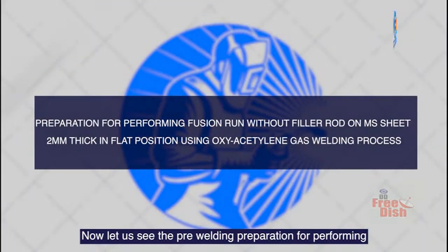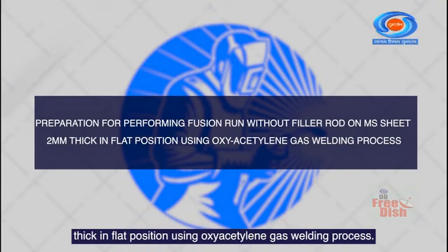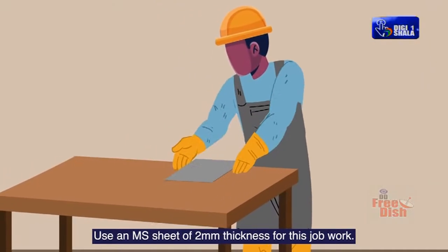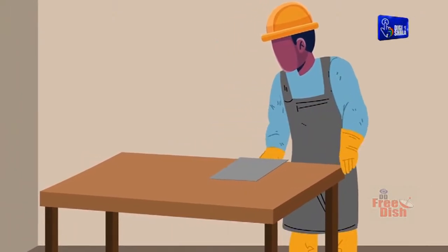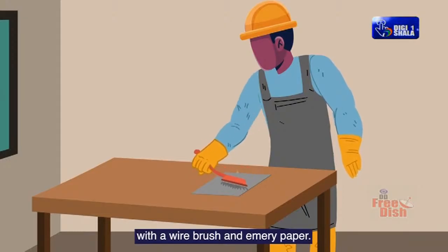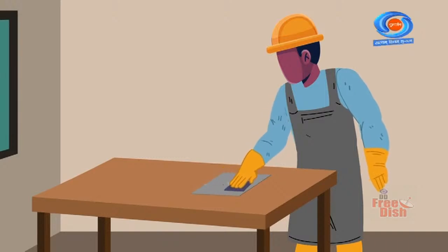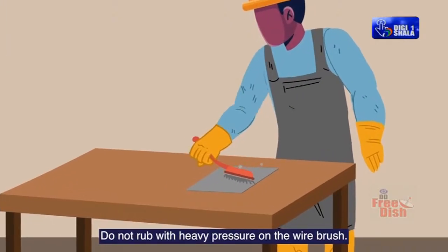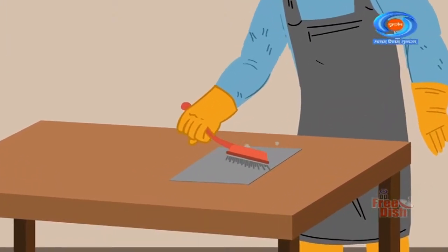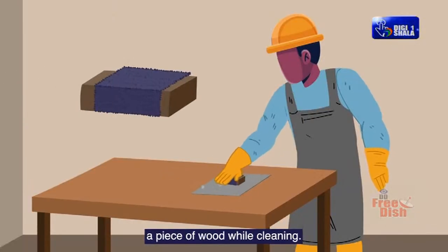Now let us see the pre-welding preparation for performing fusion run without filler rod on MS sheet 2 mm thick in flat position using oxyacetylene gas welding process. Use an MS sheet of 2 mm thickness for this job work. If there is any rust, remove it with a wire brush and emery paper. Do not rub with heavy pressure on the wire brush. Use the emery paper rolled on a piece of wood while cleaning.